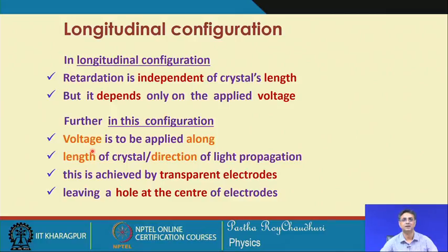This is a little inconvenient, but it is achieved by using transparent electrodes, usually titanium oxide or any transparent oxide at this wavelength, or by making an annular hole at the input side, so that you can apply the electric field from ring-shaped electrodes while the light propagates through the narrow hole in the electrodes on either side, at the input side and the output side.